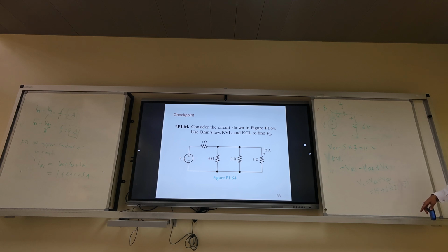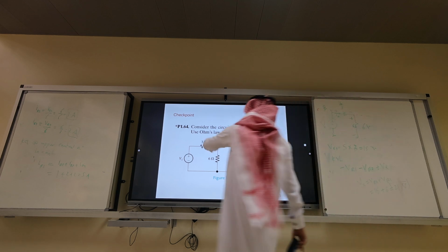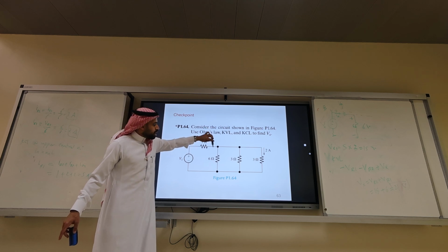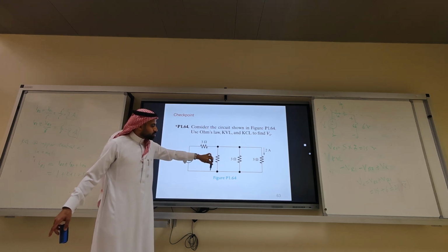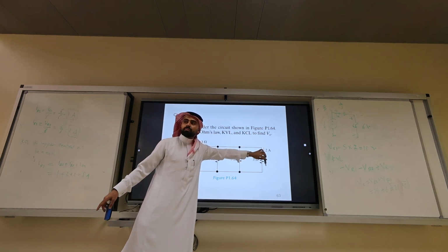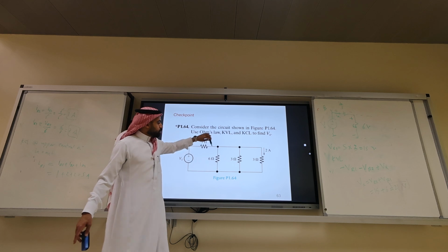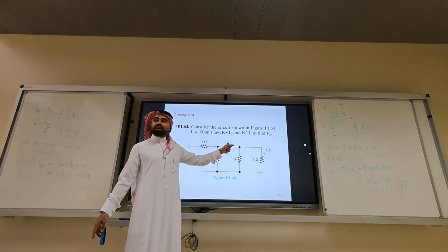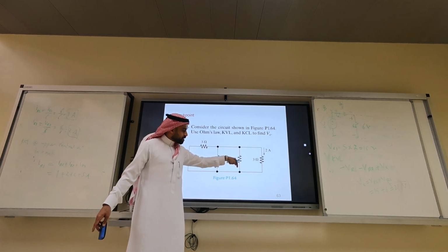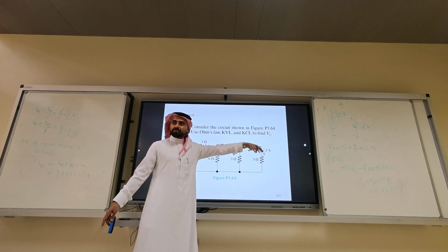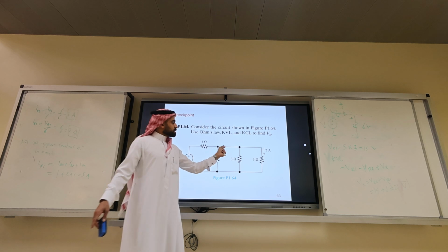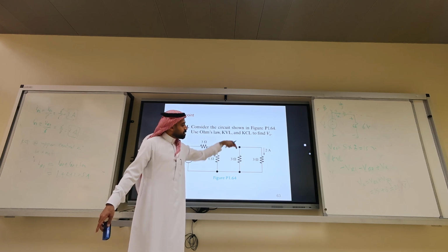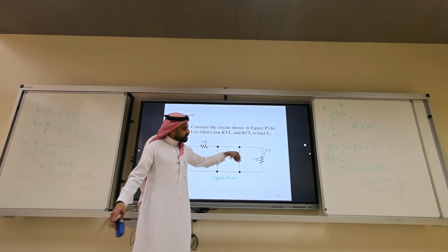Yes, please. Where did you do the KCL? We did the KCL here. In IR1, out IR2, IR3, IR4, out of the node. You're asking why we did not calculate the current here. Well, the current here is IR3 plus IR4. So let's split them again. Get it? That's a very good question. Here it's IR3 plus IR4.